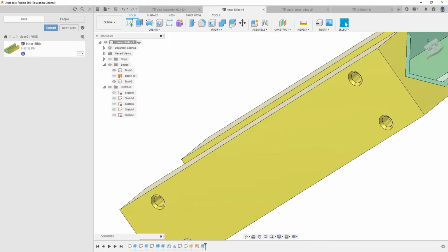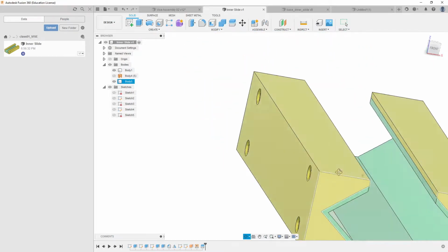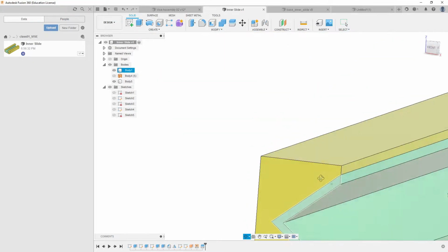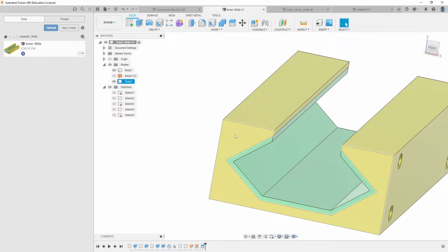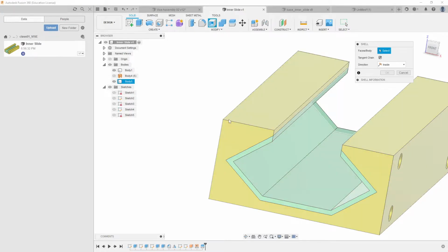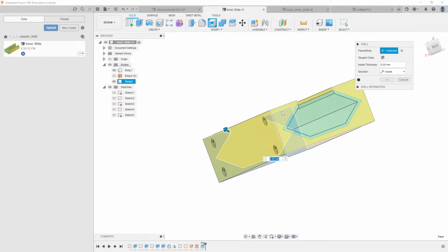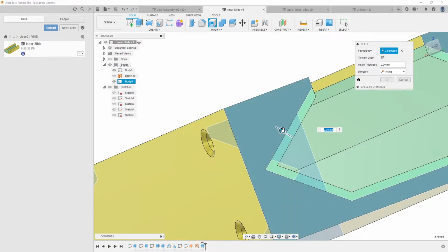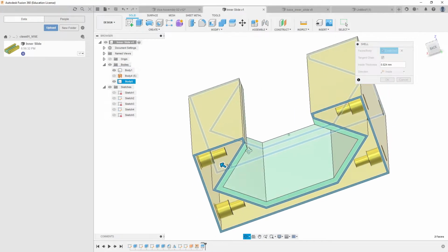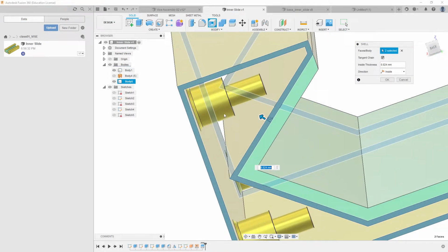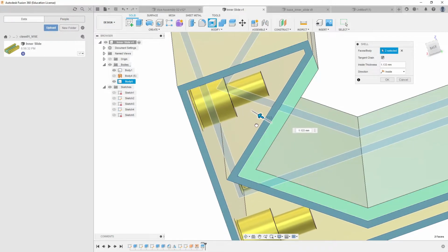So back over here, the holes that we have going through will remain holes all the way through and have structure where it's going to be hollow and maybe give us some appreciable amount of reinforcement for the body as well. So we'll go here and we hit this face there and this face over here, if I can actually pick it, and then we're going to open this up. So you see, look in there. So now we've got our counterbored, countersunk fastener holes here. You see how that works?